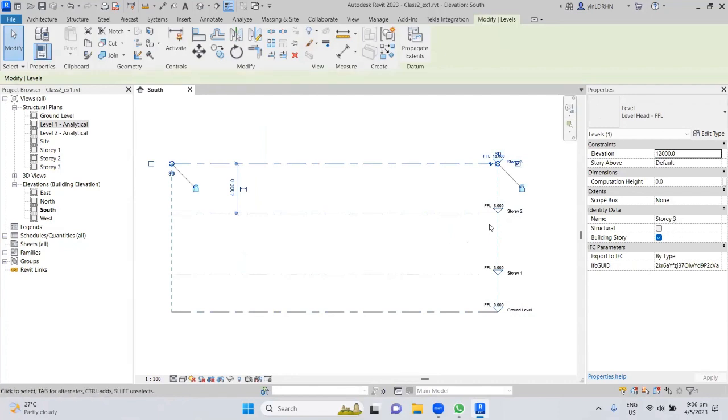As I said, a level is one kind of object. For each level you can see the properties: name, elevation, height, and so on. You can copy this level or make an instance of it. The level contains properties, and these are all already set here. That means when they created this object or family, they set up these properties. These properties are variable. You can change them.